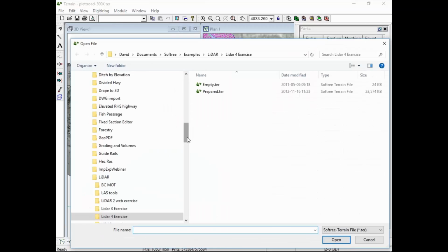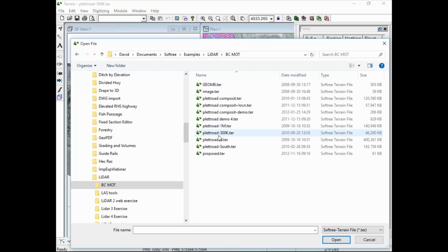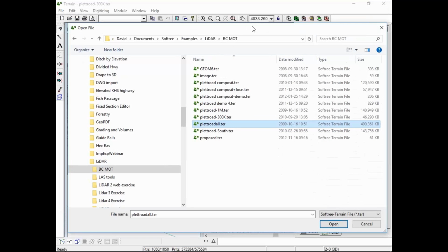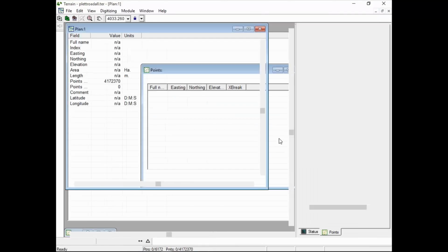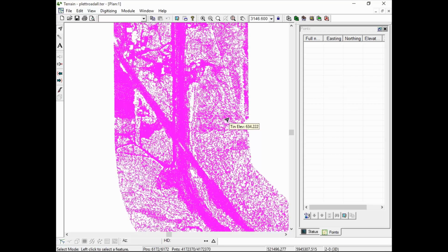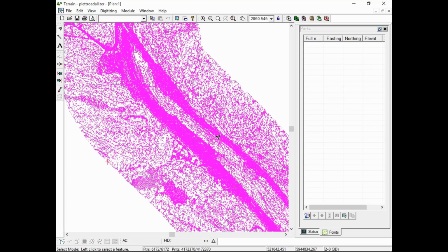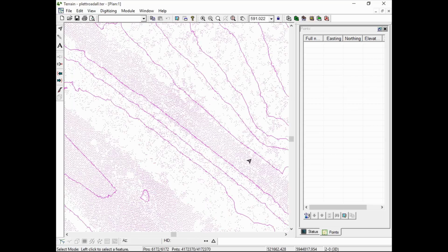is I just brought in all the data points, and this is what it looks like. So remember what that looked like. Let's bring it in with all the data points. And it's just a little bit more dense. So I get a more accurate surface, especially in this area here, it looks like this is a railway track actually. Again, you can see that there's dense points where there's no foliage and not so dense points where the trees